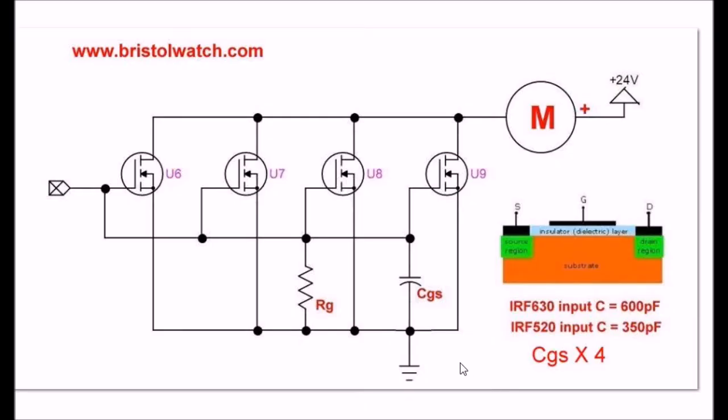Welcome. The subject of this video is connecting power MOSFETs in parallel. I got an email from a visitor who was having all kinds of problems using one of my circuits when he connected MOSFETs in parallel. The question became about RG. RG is used with these MOSFETs to bleed off any static charge, thus enabling the MOSFET to cut completely off.